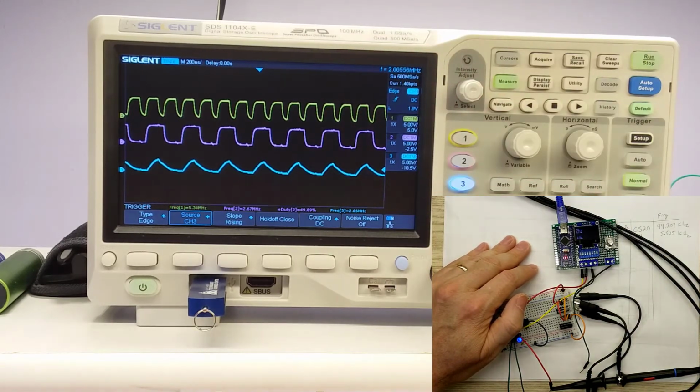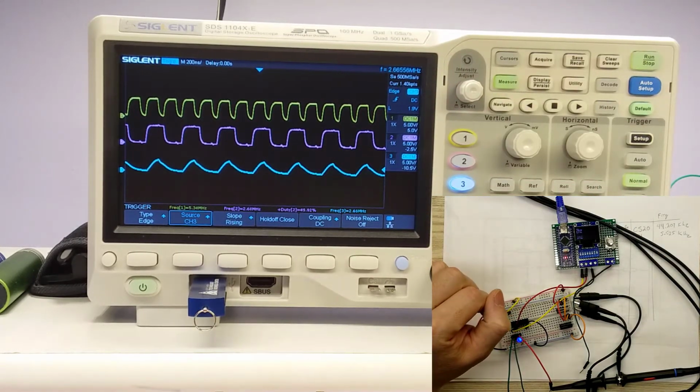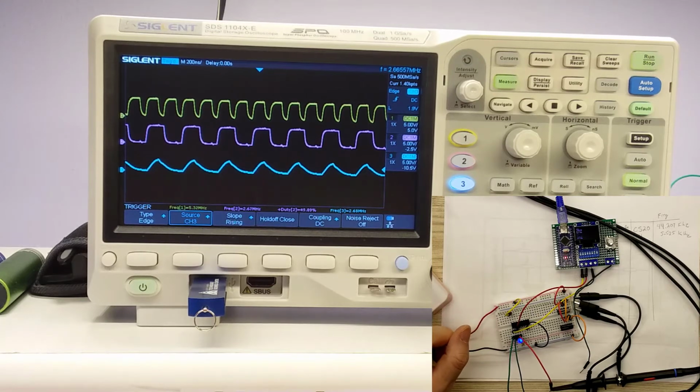This is actually 200 nanoseconds. I'm not sure if the datasheet said specifically what the frequency on that was that it supported. So with this test, channel 2 is exactly half the frequency of channel 1. Let's change it so that it's completely out of sync, and we're going to adjust a little PWM circuit for the second input and see how well that handles.